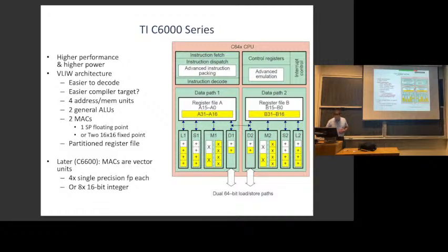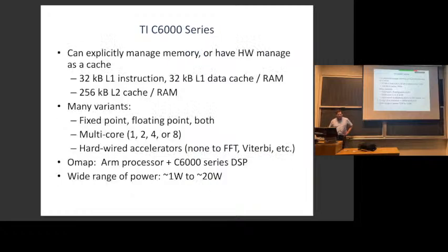Okay? And then some later versions of this basically added SIMD instructions. So everybody likes SIMD instructions. They added instructions that could do 4 floating point multiplies instead of 1. Okay, I don't think I'm going to talk too much about the details of this. It basically has small L1 and L2 caches, and it's kind of like a GPU.